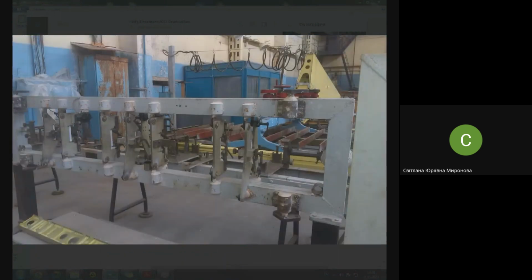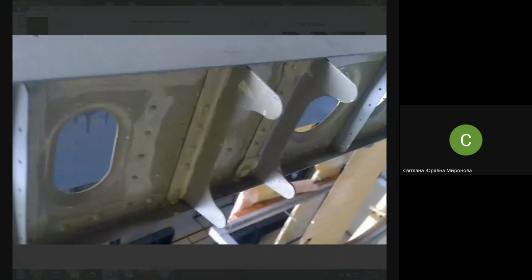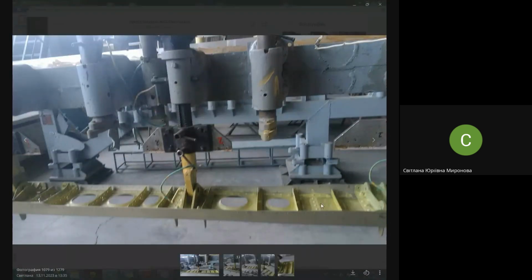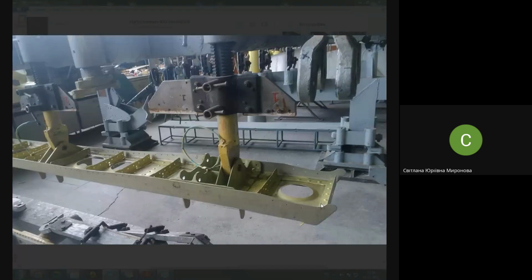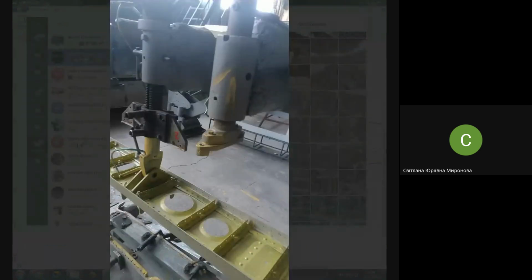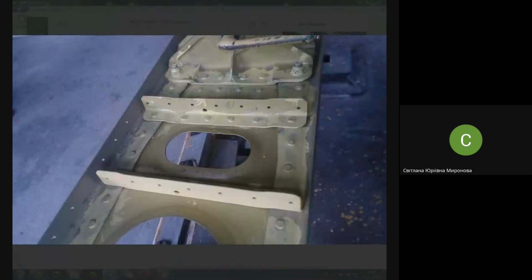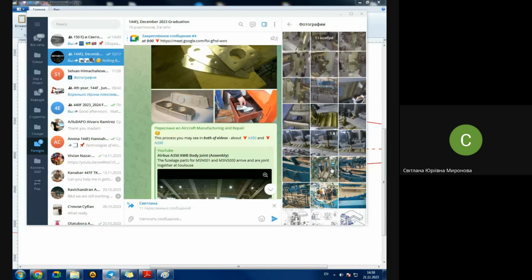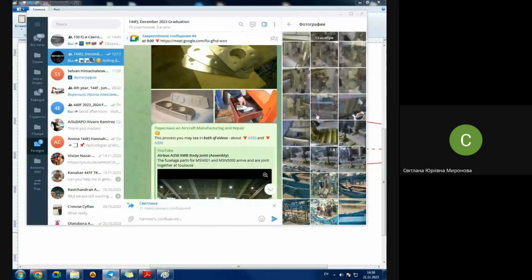Something like this. And what do the jigs look like? Let's take a look at the locator first, so that you might imagine in a more general way what this spar looks like. Finally, a spar very similar to what you see, but it's already in the next jig. The next jig is the jig of rudder assembling. It's not spar assembling anymore, it's rudder assembling. And this spar is actually more complex with respect to the rib we are talking about, because this spar is with brackets.